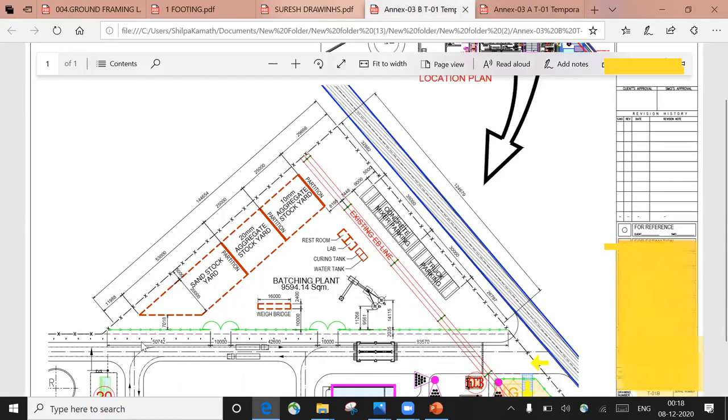So this is how it looks. This is what we saw now. It's a blown up diagram that you can see here. This is the entire location that I have. So you can see here, right? We have a sand stock yard here, right? Because in order to prepare concrete, I need cement, I need a fine aggregate, that is sand, I need coarse aggregate. So that is why they are storing the sand somewhere here, that is called the sand stock yard. In the same way, we need 20 aggregate. So again, they are going to store the 20 aggregate here. Along with that, we have to use 20 downgraded aggregate, that is 20 along with the 10 we are going to add. So again, you can see here 10 aggregate will be stored here.